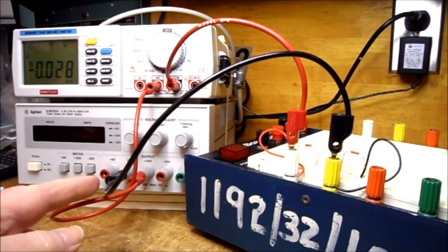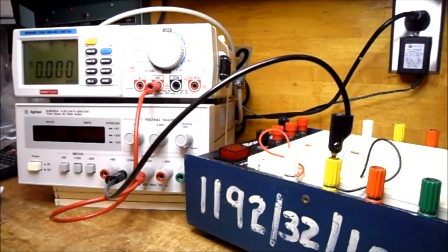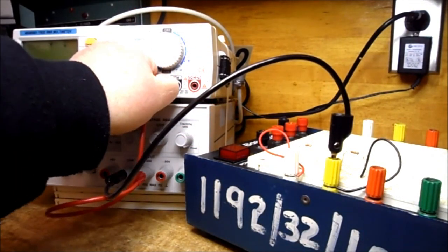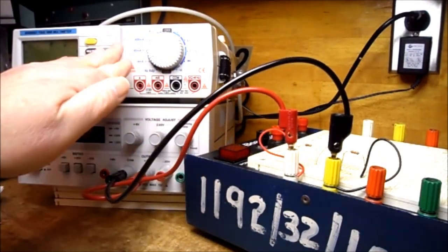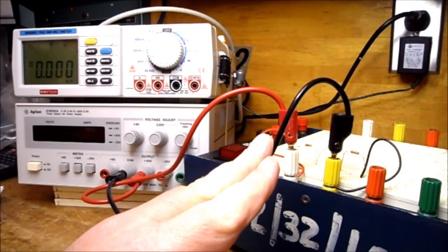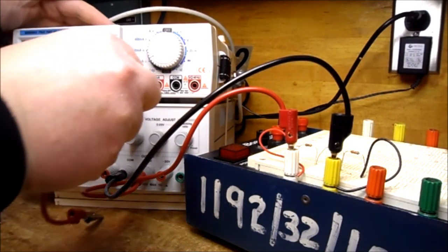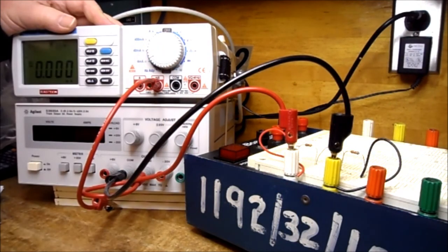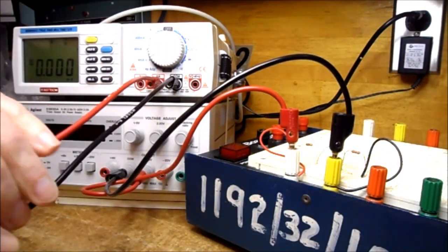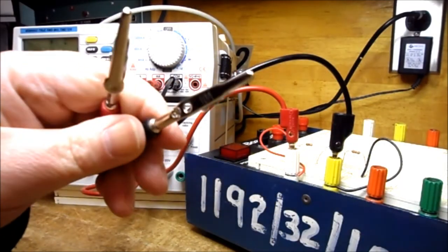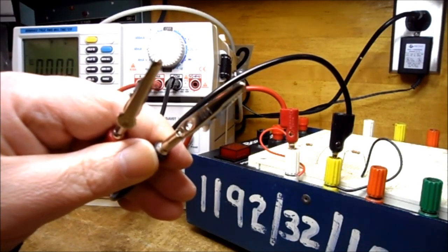Now we're going to disconnect the ammeter. So I'm going to take out the red lead from the common, and I'm going to take out the red lead from the milliamp and put it into my circuit. So now I do not have an ammeter in my circuit at all. So my next step is to put the red lead in the milliamp hole and another black lead in the common hole. So I can now take these two leads with the alligator clips on and put them in my circuit. So I'm going to show you where to place these in the circuit now.